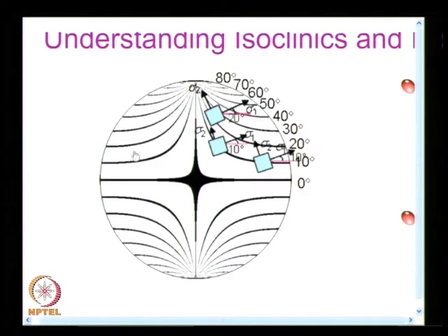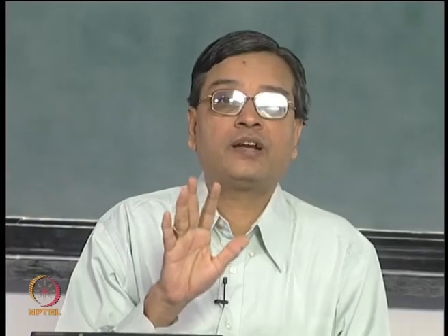You do not see this information available in one experimental exposure. This is what you have in conventional photoelasticity. That is why people asked, can I plot the isoclinic field for every point in the model domain, and digital photoelasticity has now achieved that. You may have to take a few images and process the intensity, and it is possible to generate plots of this nature by post processing the data acquired.